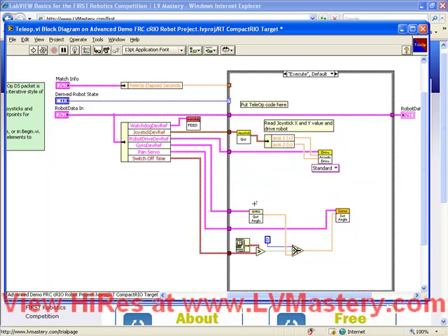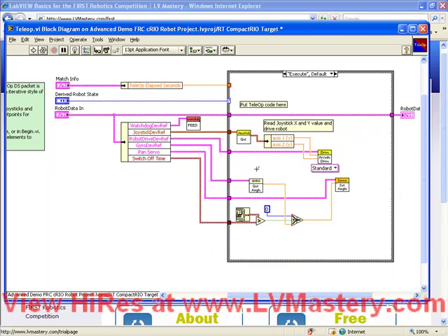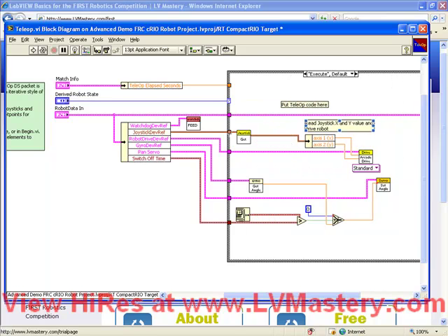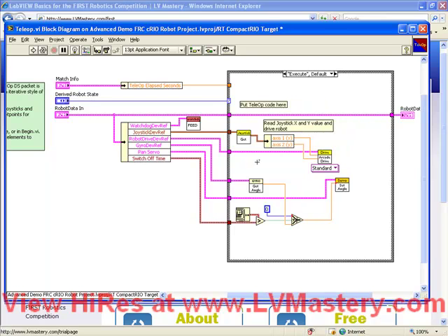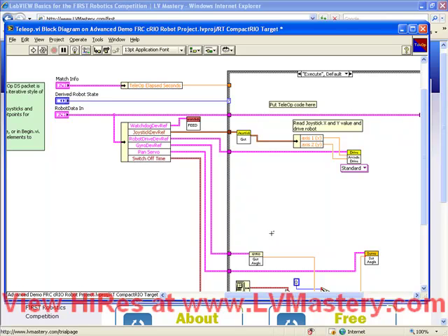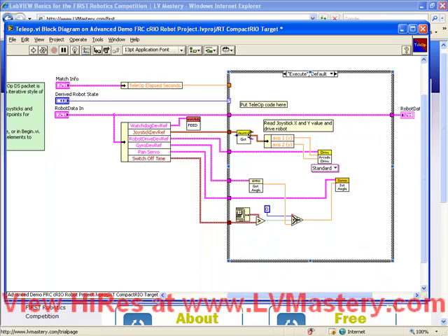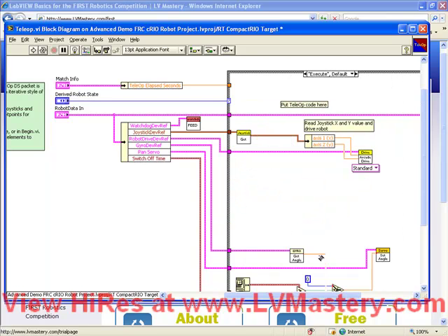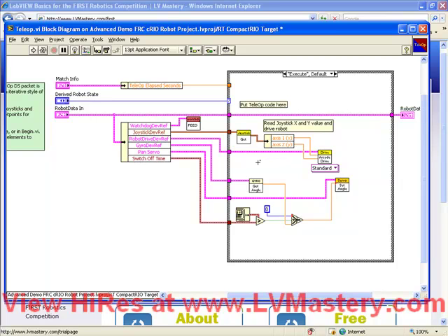And you see what that does, it inserts space in your block diagram. You have to be very careful when you do this, because if you drag strictly vertically or strictly horizontally, it will only create space in that direction. But if you drag in a rectangle, it's going to move things in both axes. And if you've already taken great care to line up your wires and your objects, you can easily move them around into locations you don't necessarily want them when you create space this way. So my advice is try your best to only create space in either a vertical or horizontal orientation.